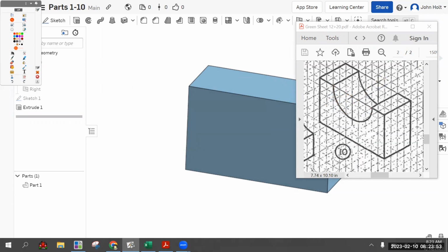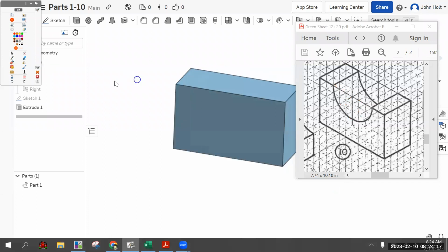Oh no, the internet. Give me a second. Oh, we're back. The only thing we need to do is find the center point. We know we have a radius of 3. It's the same distance in every direction. We're just going to make a circle with a diameter of 6 and then cut extrude it over, making sure that the center point is this top center point, which we'll get a free snap to. We don't even need to dimension it.